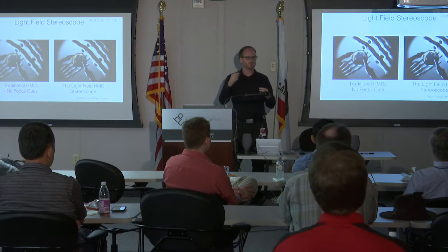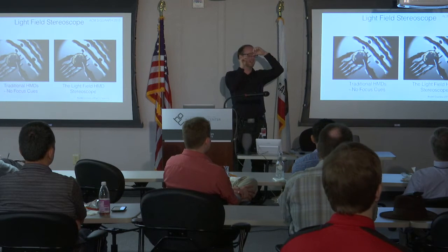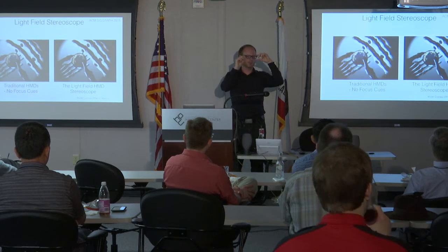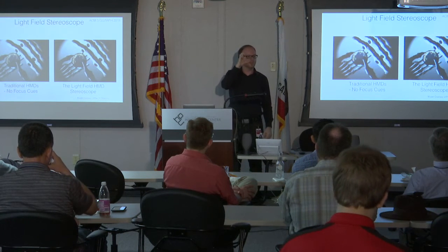But basically what we're trying to recreate is we define the eye box as a 1 centimeter by 1 centimeter region around the pupil so that your pupil could move within that and it can expand and shrink. And basically if we can recreate this light field entering the pupil, your pupil can do whatever it wants. It'll always pick up the right rays and create a realistic image. So that's the 4th dimension. Then if you add time, it's 5.